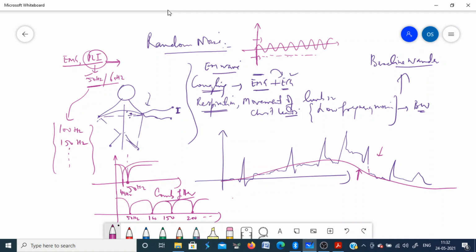Even if the frequency of the noise in the signal changes, it will adapt its response according to the noise frequency. It will have a moving frequency response basically. Its null point can go from 50 to 49 hertz, or from 50 to 51 hertz, depending upon the frequency of the noise in the signal, and we call these adaptive filters.